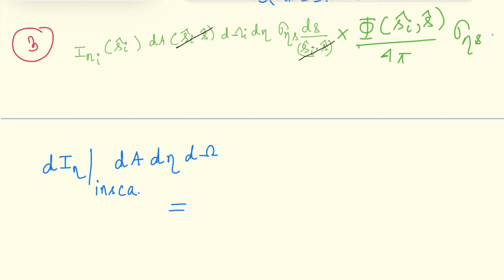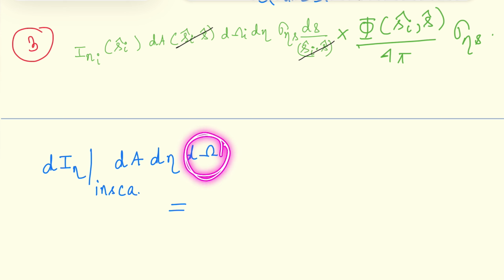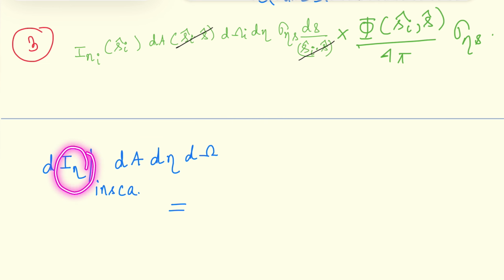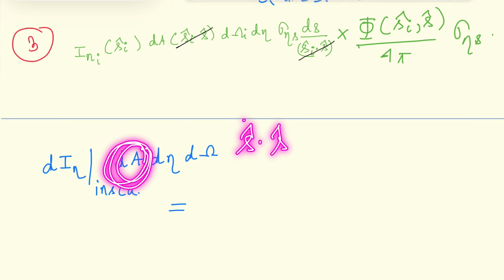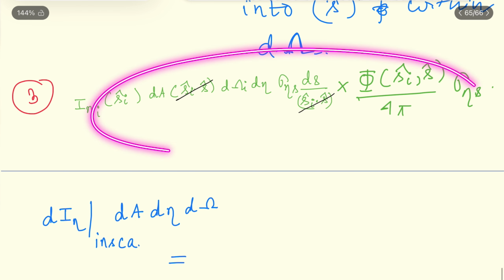So this is the total energy that is being in-scattered in the solid angle d omega, and also in the direction S cap, that is a function of S cap. And I need to multiply also these areas. Obviously you can argue with me that I should have multiplied this, I mean S cap, but actually this ray is already travelling normal through this area. So this will be S cap dot S cap, and that is 1. Okay. Now this is equal to this whole part.